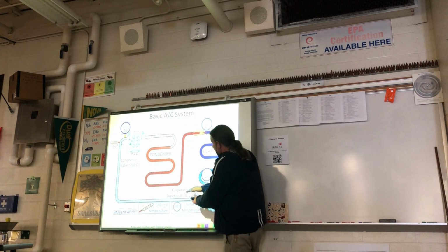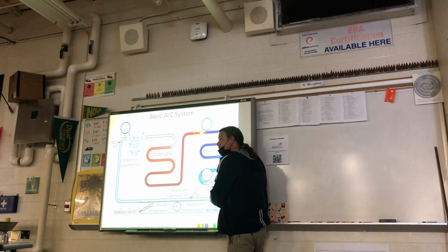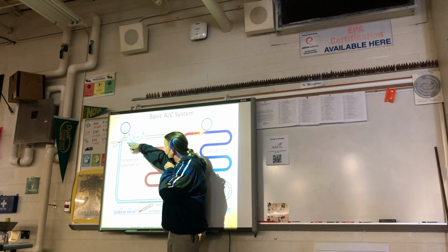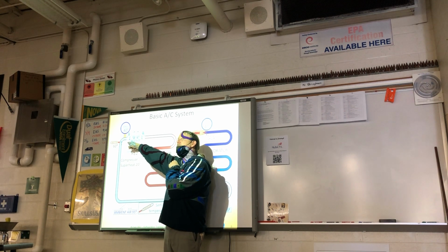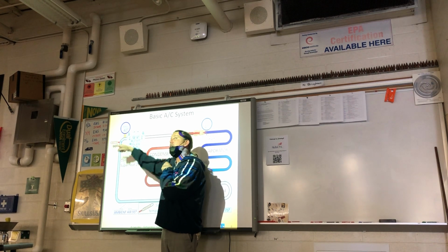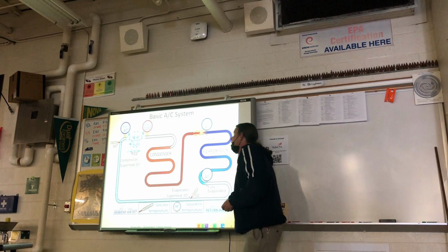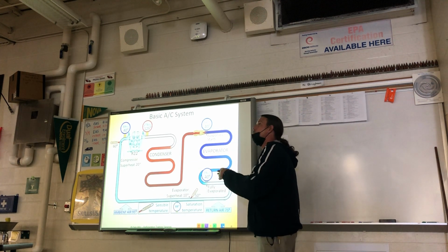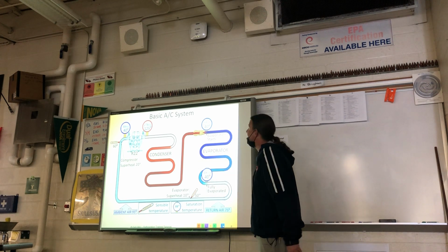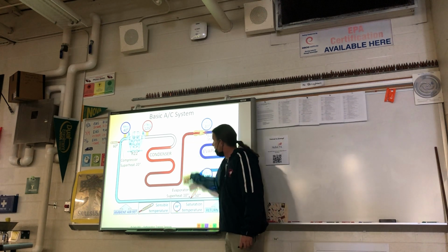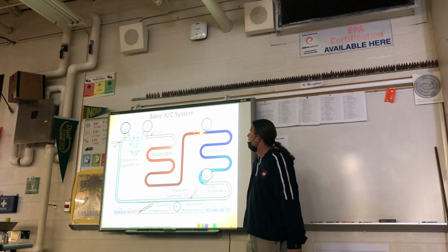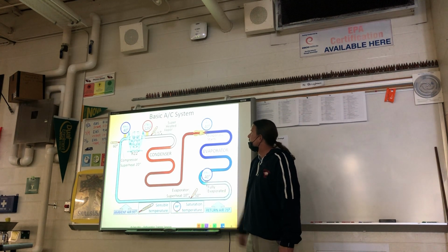So I've got my evaporator superheat measured right at the exit of the evaporator, and I've got my compressor superheat measured right about 6 to 12 inches away from where the suction service valve is on the compressor. All right, and that's usually going to be warmer than the evaporator if it's a really long pipe run. If the liquid line and the suction line that you're running from the indoor to the outdoor unit are really long, sometimes you've got to add some refrigerant for that.